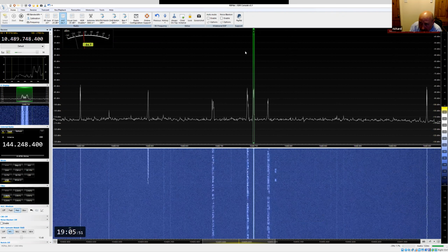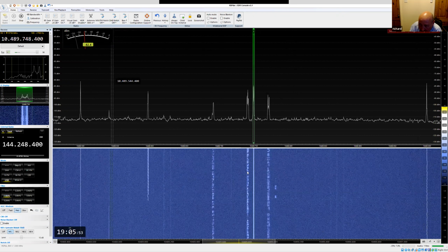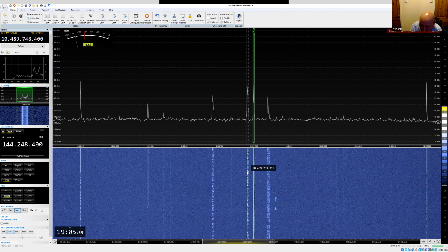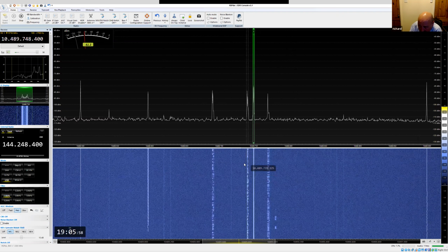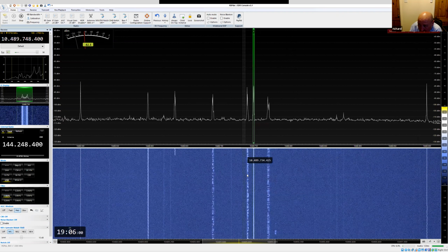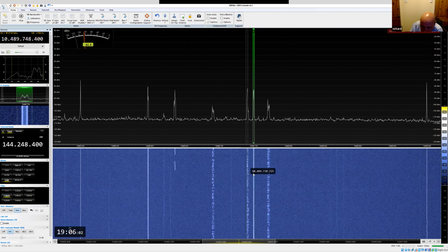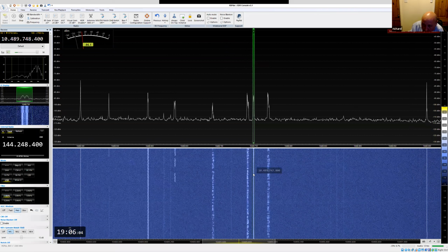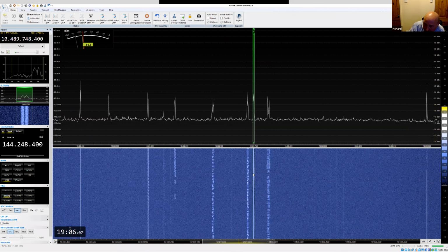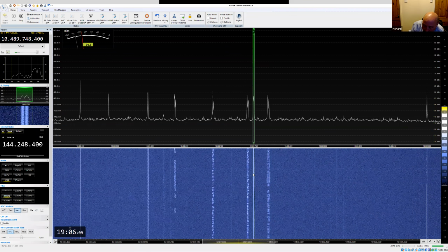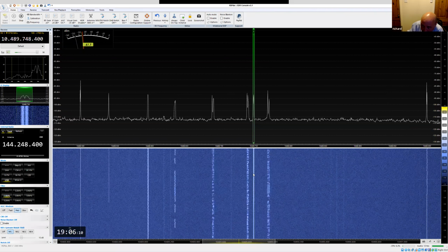You can also use one of the beacons to lock your system. So for example, most people tend to use the center beacon and lock onto that, and then if your LNB does move, it'll basically take into account the offset from the LNB, and it'll track it with the transmit side.